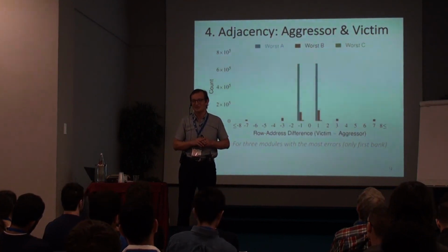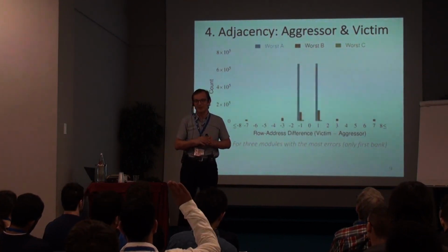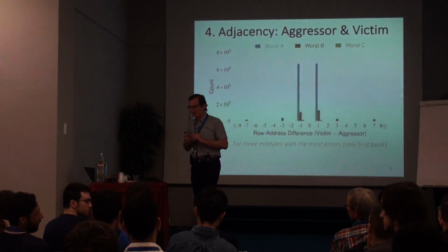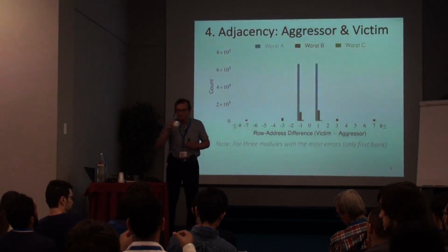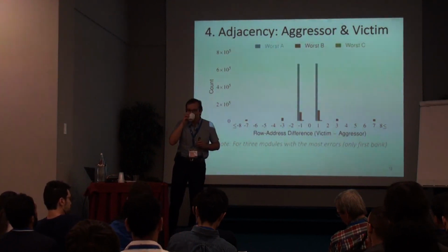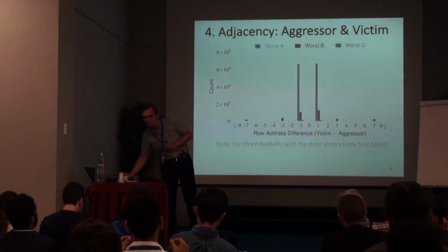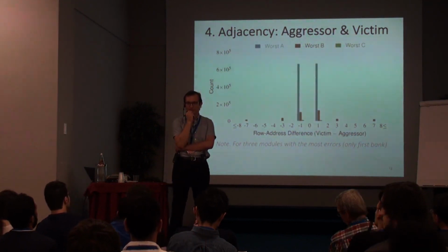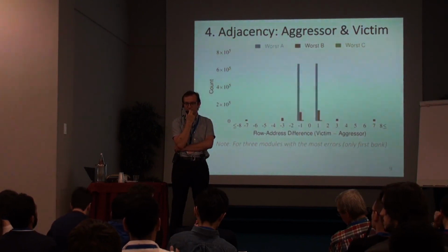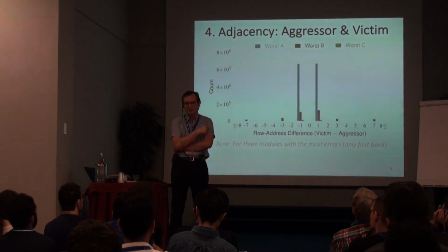Yes. So you mentioned the need for intelligent controllers. But the controller usually sits outside the DRAM chip, right? So if a whole DRAM package fails, the server operator needs to replace that. And in that case, the online profiling of the DRAM is to be done again by the controller or things like that. That's right. If you replace the DRAM, you need to have a new profile.